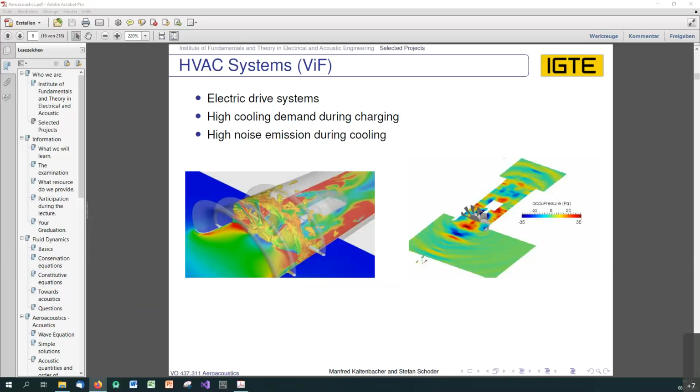When these structures then hit another structure, so for instance, here you have the blade of the rotor. Can you see the cursor? Okay, perfect. Here you have the blade of the rotor. There are vortical structures developing and traveling in the duct. And then these vortical structures probably also hit the electrical motor in the backflow, and then interact with the structure. It even emits more sound.